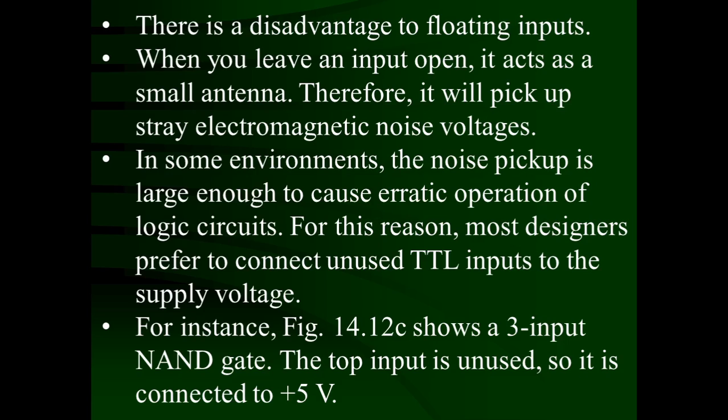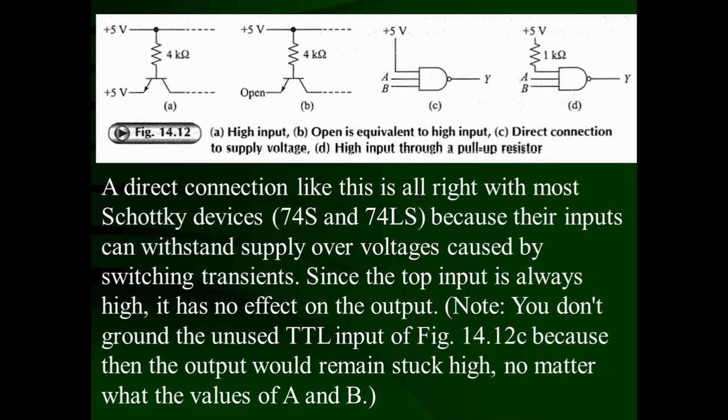For this reason, most designers prefer to connect TTL unused input to the supply voltage. For instance, figure 14.12c shows a 3-input NAND gate. The top input is unused, so it is connected to plus 5 volt. The same thing you can see in this 14.12 A, B, C and D figure.